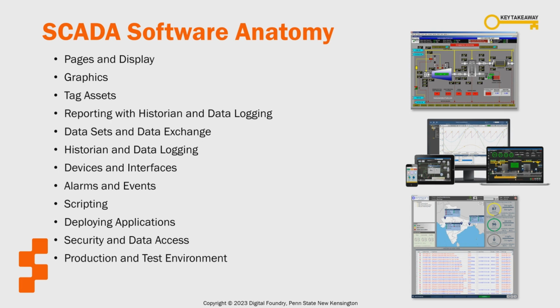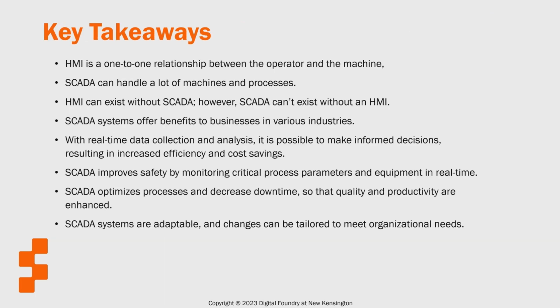Security involves firewalls to separate process control networks from the administrative networks. Now, once your project is built, you will need to test it before running in production. So you need to look for options to trace functionality and property watch windows to track your code when it's running. Key takeaways. To implement supervisory controls, determine how the ISA 95 automation pyramid fits your facility.